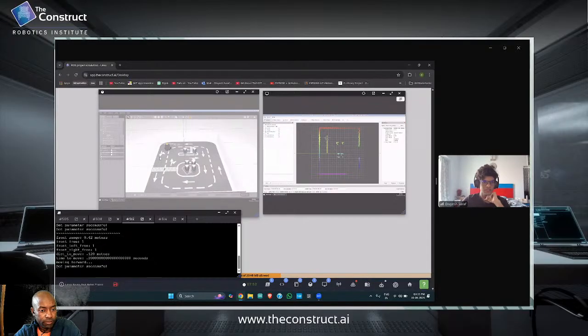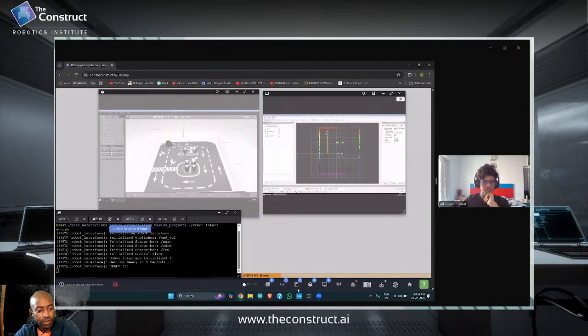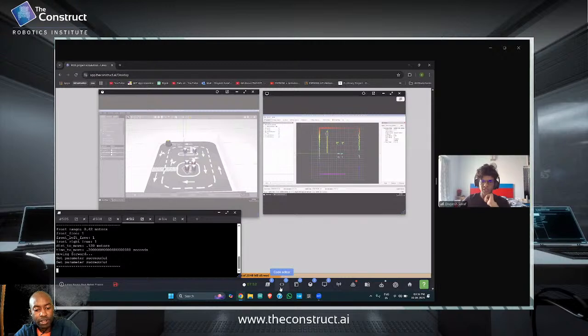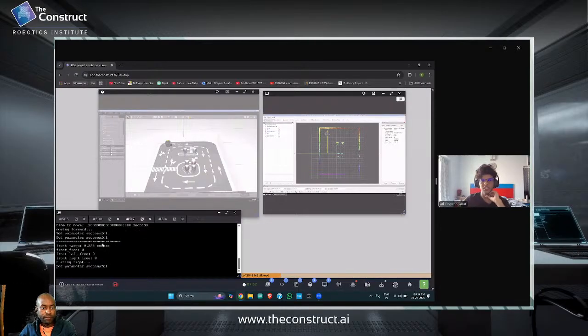There's still some space left, so it decided to move. Okay. Well, what threshold did you use? Threshold, I just used the threshold that was given. Okay, 0.3. Alright. So now it should take a turn because the 0.6 threshold is not there. As none of the directions are free, it will decide whichever direction has more distance. Okay. So if your right had more distance compared to the left, it turned a certain amount to the right.